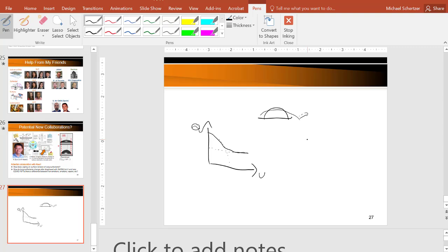Yeah, so the way I would normally measure surface energy is with a pendant drop, or a droplet on a surface, and you can do a series of different measurements on known surfaces and then on whatever surface you have. I can go over that with you if you'd like. We can talk about that a little bit. So you're trying to measure the surface energy of this almost gelatinous material, right? Something like PDMS, an elastomer. Right, that's correct. We can sit down and think about that.